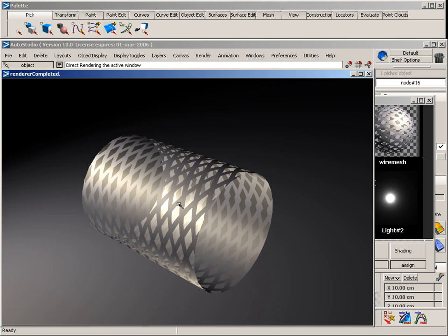However, the highlight is still going over the entire surface, treating it as if it was maybe some printed clear material. And the other thing is that in ray casting, the moment I put transparency onto the shader, I lost the shadow. The shadow you will only be able to get back when you ray trace. But first things first, let's start to get rid of the highlight area in the transparent areas.